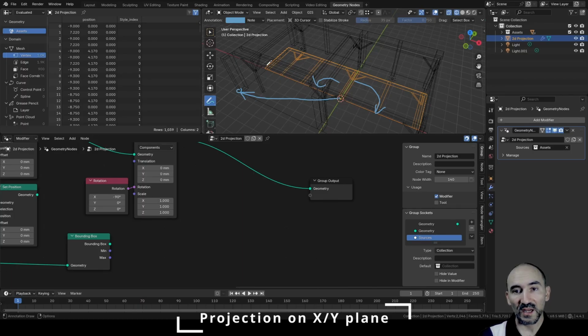In this way I would have a bounding box with 0 for the height, and this point for the minimum and this point for the maximum, and move all the objects and all the lines by this offset. So this offset is exactly the difference between the position of the minimum of the collection and the vector of the minimum of our 2D projection.